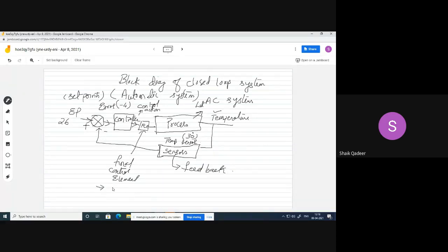Yes, sir. The excitation to the compressor and the excitation to a fan. So what this control action does is continue the action supplied to the compressor as well as the fan, so that the surrounding temperature of this AC system goes down, and in the next iteration the read value will be smaller than the last case.